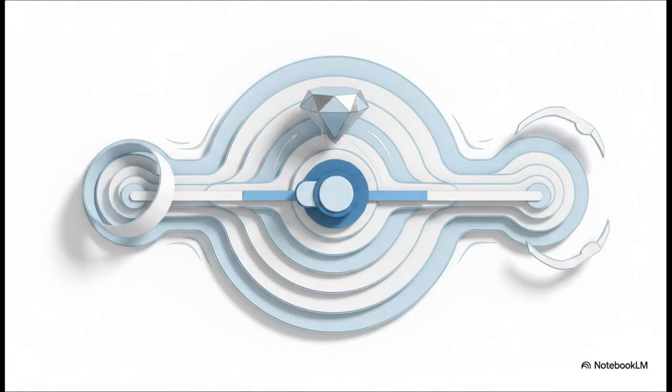Let's actually trace how that ripple effect sequences out. You nudge that slider, right? Instantly, the ring size diameter shifts, and because you built a flawless chain, that shift pushes the shank surface outward. That outward movement then carries the entire gemstone setting up to a brand new height, which then automatically forces your claw positions to recalculate. Keep in mind, we're working in a field that relies on crazy tight tolerances, like 0.1 millimeters, yet the slightest slider adjustment recomputes all your shanks, bezels, and claws in real time, and you didn't have to redraw a single line. It's brilliant.